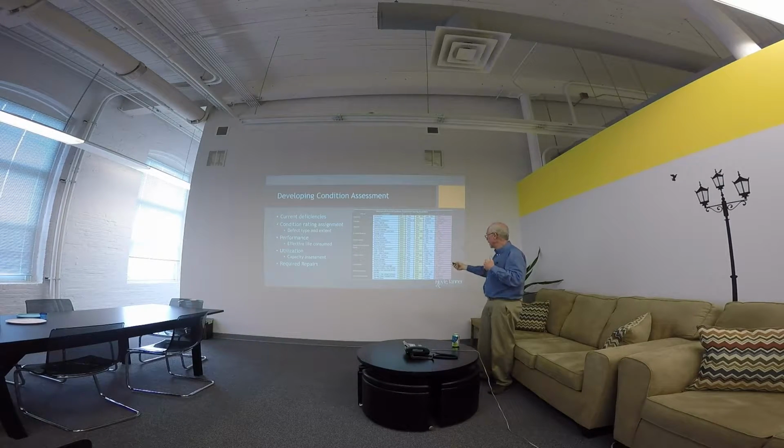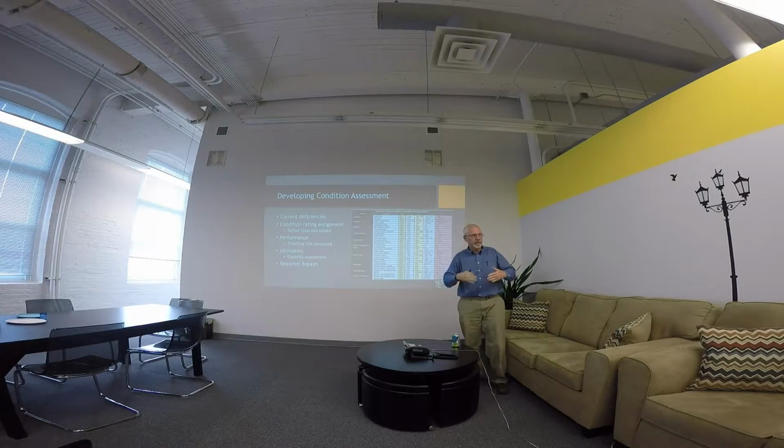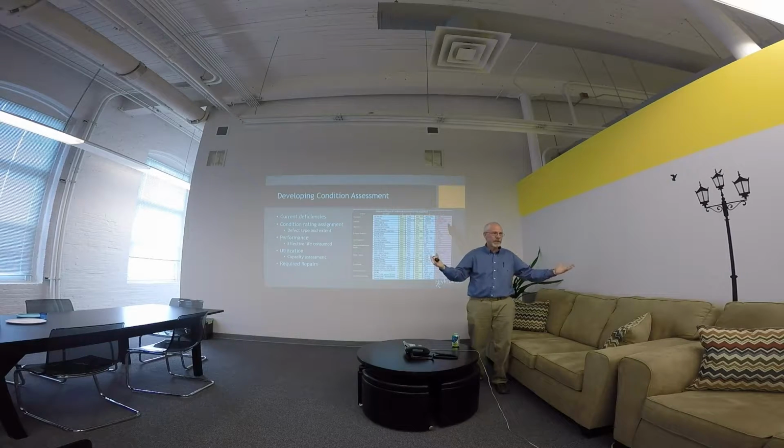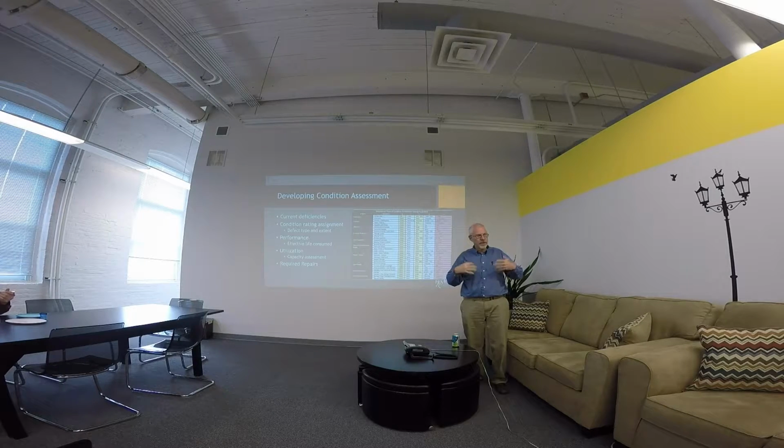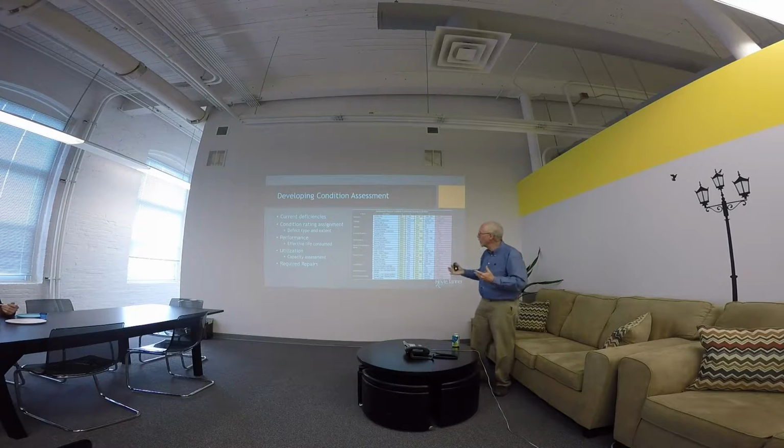If we look at corrosion and look at surface only, it's not going to fail if just the surface is rusted, but it's an indicator. The military looks at rust very critically, and that's probably the highest expense of all military costs. So when they see rust on the surface, they address it because it's an indicator that it's deteriorating, and they want to get to it before there's structural corrosion. So they look at that.